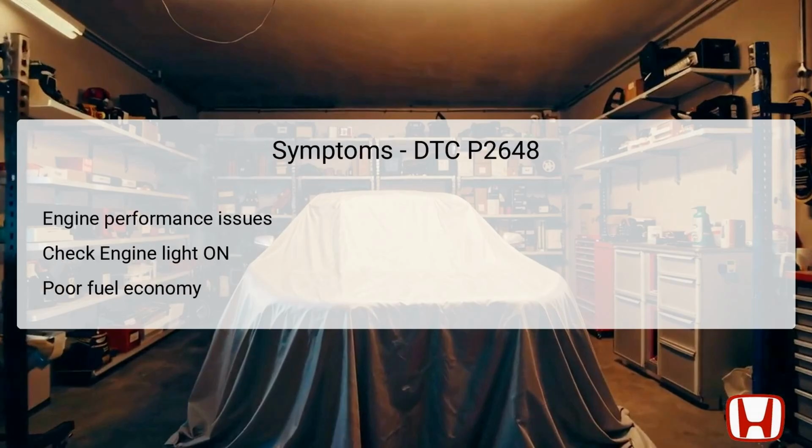The symptoms associated with DTC P2648 can significantly impact vehicle performance. Drivers may notice a lack of responsiveness from the engine, especially during acceleration, signaling possible performance issues due to valve timing discrepancies. The check engine light will also illuminate, alerting the driver to a potential issue requiring attention.